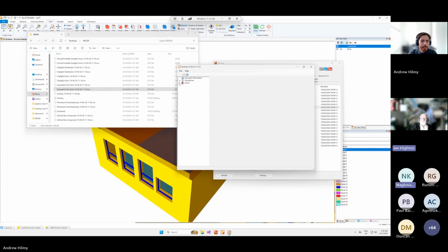Yeah, Jason, and we've got some questions on this section. Jason just asked, how do you zone an imported DWG, which is a good one. Usually what I do is I import the geometry as it is, and then in the 3D view, when you've got the imported geometry visible, you can actually use the 3D selection tools to select walls. Then you can click on a wall and copy it to a story, and you can do that for the walls that you're interested in, and then just zone that space.